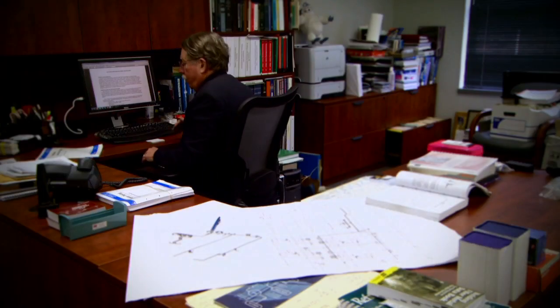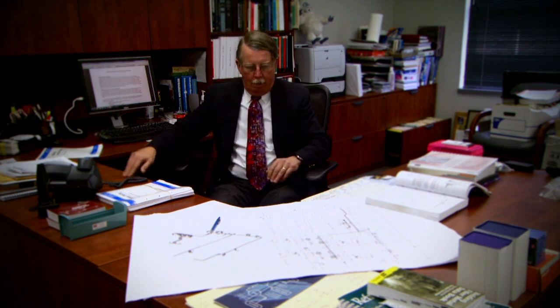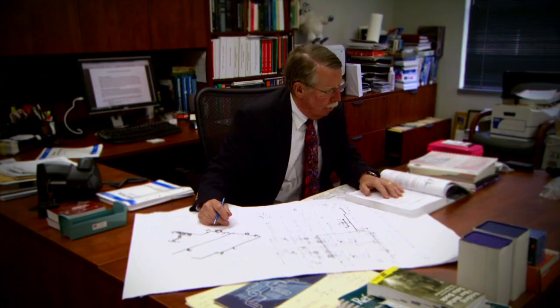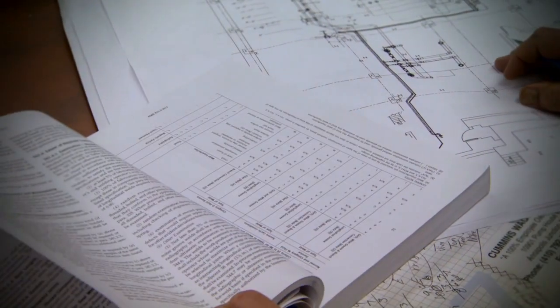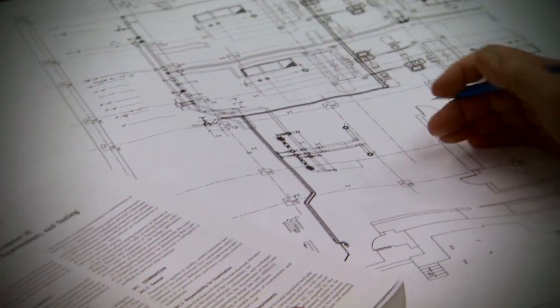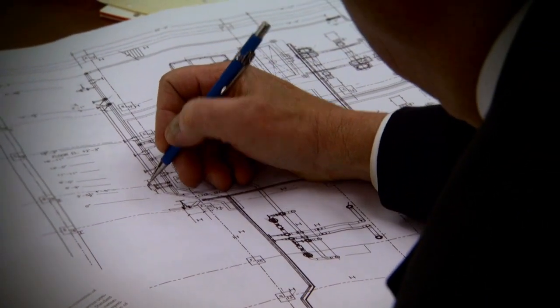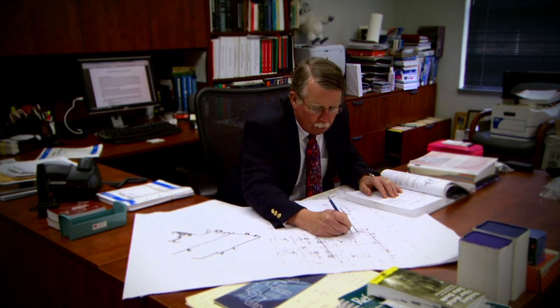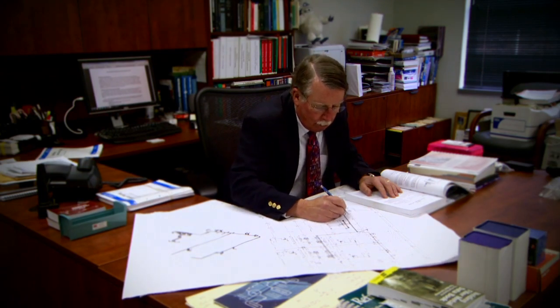Once the appropriate B31 code section has been selected, the engineer should proceed to select the appropriate materials and determine the pipe sizes and schedules, lay out each system, and perform the required design and analysis calculations. The engineer's design specification should impose the same B31 code section that the contractor will use for the installation.